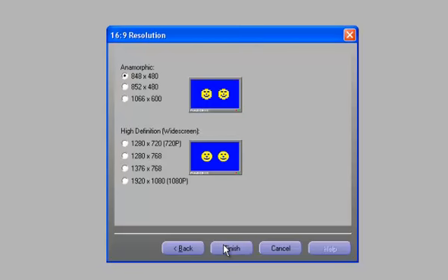And then here we need to select the resolution for the project. Now, larger numbers typically translate to more clarity on screen, so those larger resolutions are usually more desirable. The limiting factor here again is going to be the display itself. So you will need to reference the display's owner's manual and consult the specifications section for the preferred resolution for the connector being used, whether that is VGA or DVI. There will be a preferred or an ideal resolution. So we'll just select the option closest to that from this list that matches that documented resolution.